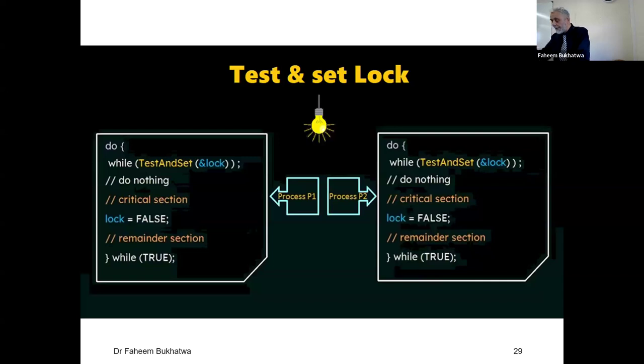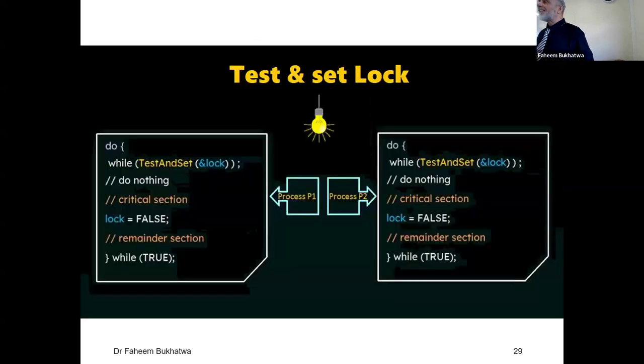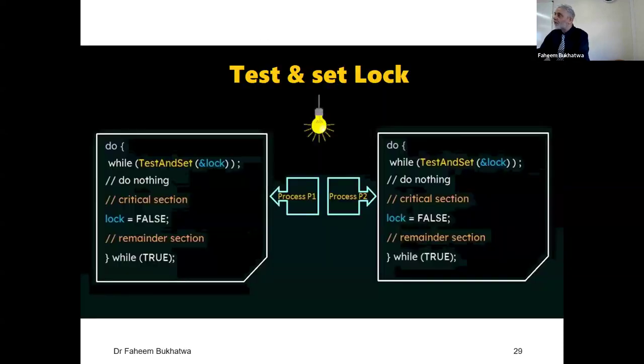So this checking the light first, looking at the light, is it on or off? They say it's off. Okay, Tom, switch it on. I'm talking to my assistant here. My assistant switches it on. And then we go in. That's not good. Why? Because maybe at the other end, another user came in and looked at the light and it was off, and at the same time they hit the switch and turned it on, and they go in as well.